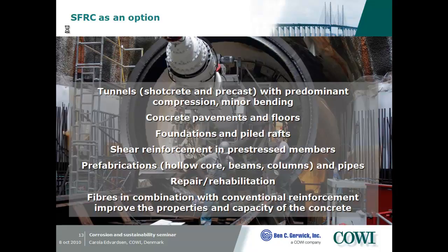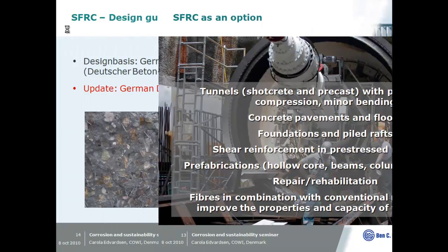Case where the crack width criteria is the case which determines the amount of reinforcement. And steel fiber could help us to reduce the amount of traditional reinforcement because they can minimize the crack width. And this is what we are now investigating more in Europe, to use this combination.